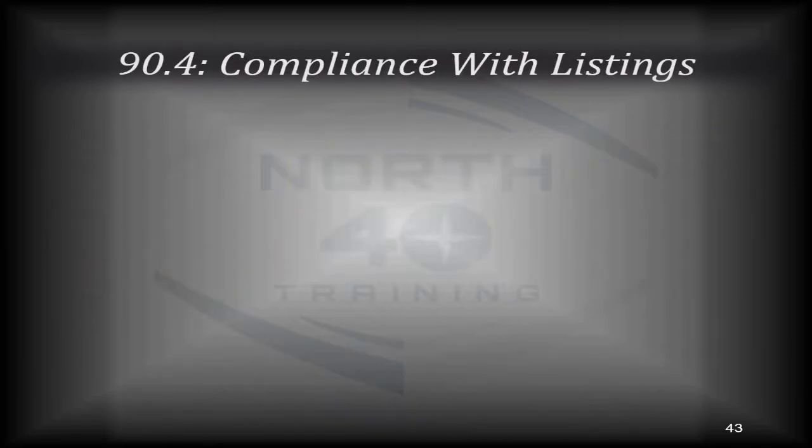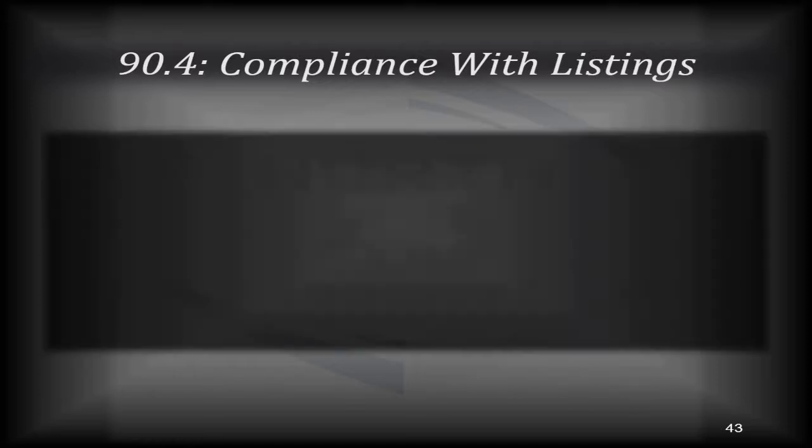90.4, compliance with the listings. It's the responsibility of the AHJ to make sure all appliances and equipment are installed according to the manufacturer's guidelines. This is in addition to following the National Electric Code guidelines. This is not instead of following the guidelines, but in addition to. Now, what are we talking about here? Well, let's give a very straightforward example. What happens if following the code violates the manufacturer's guidelines?